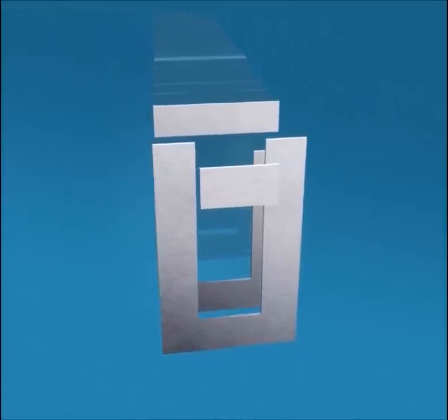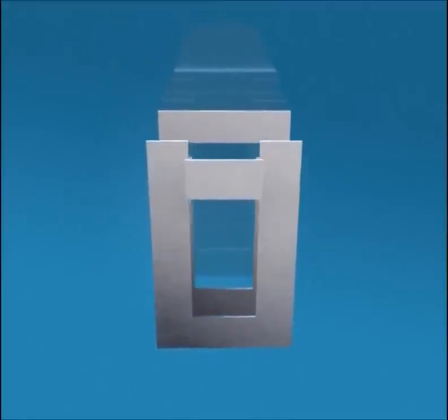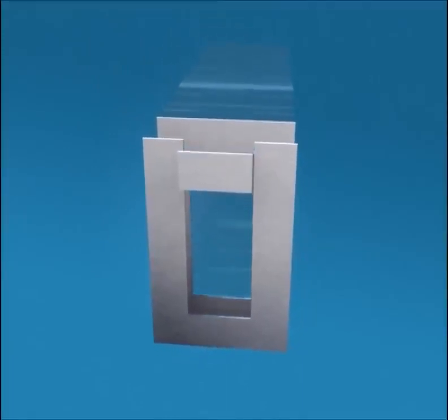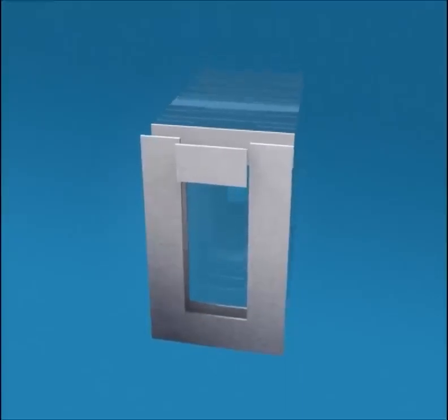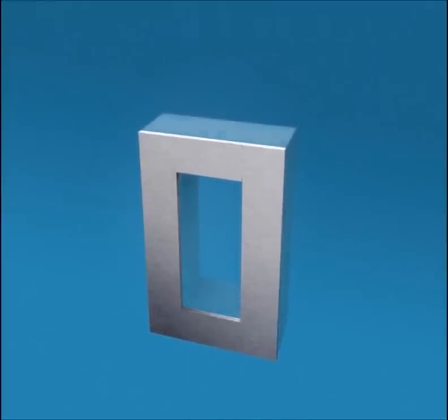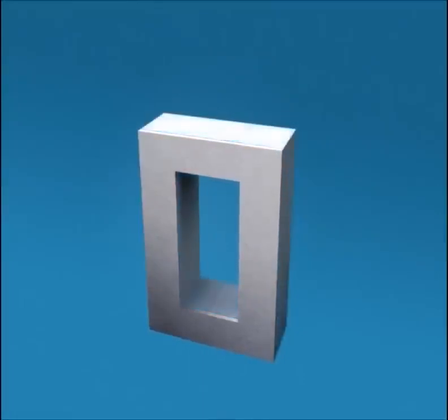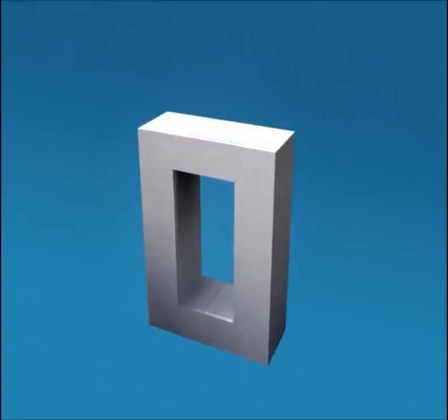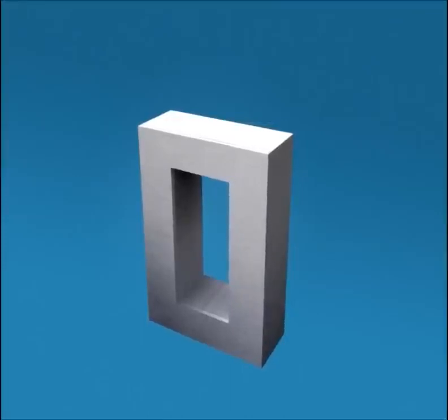To reduce these unwanted power losses, thin steel laminations are used to construct the transformer core. Laminations are made of a highly permeable material, that is silicon steel. These laminations are assembled together to build a solid core.